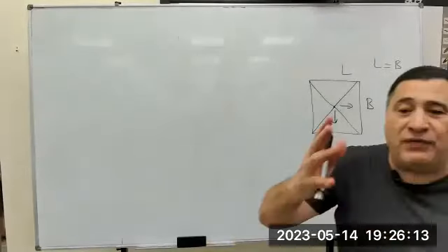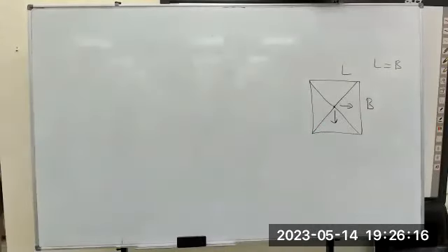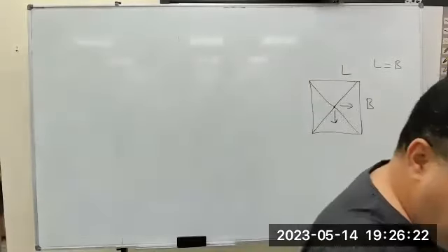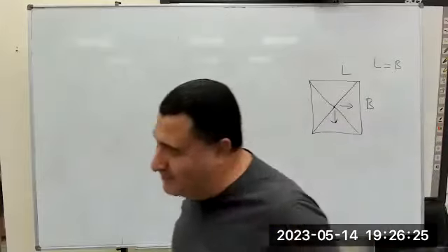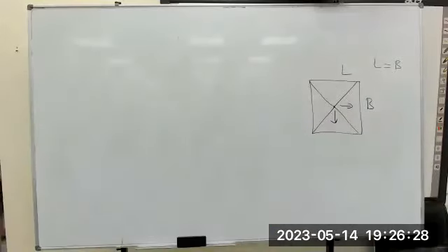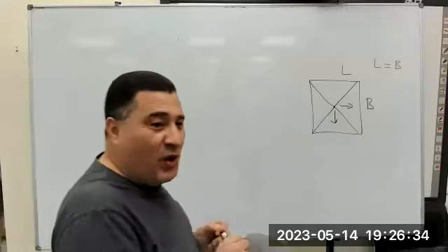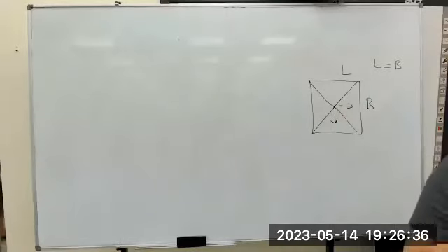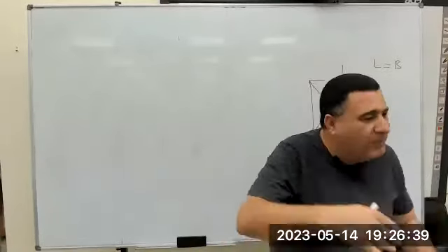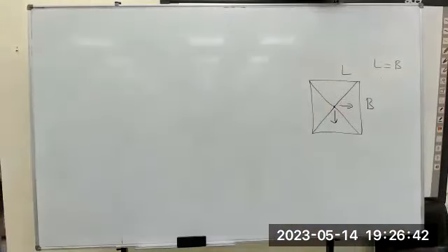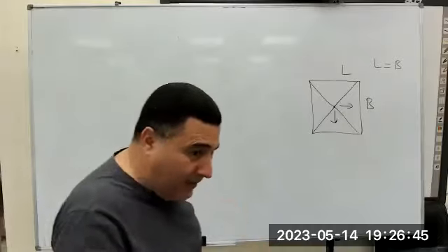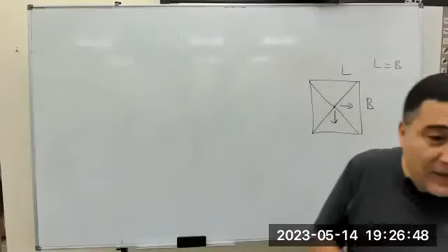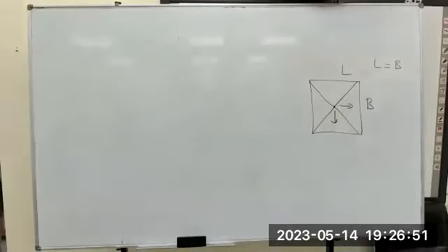These days we have a lot of software, and you can design it by your own calculation. This is what we study. Correct? It's easy for us. But if you have a stadium, like 974 stadium, it is different. The art of engineering, it will show up here. How? Because this is unique. It's not conventional. It's not slab to beam to column. No, it is different. You have to define the load paths exactly, otherwise there is a probable fatal mistake in design, and this building could collapse. The load path is very important.